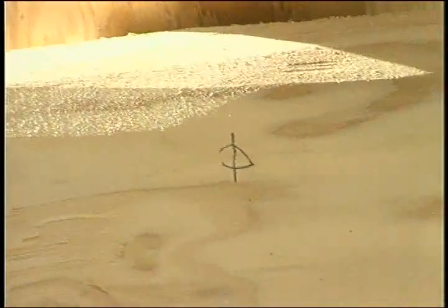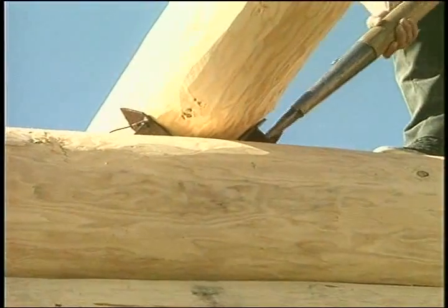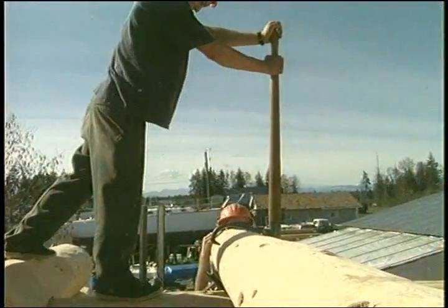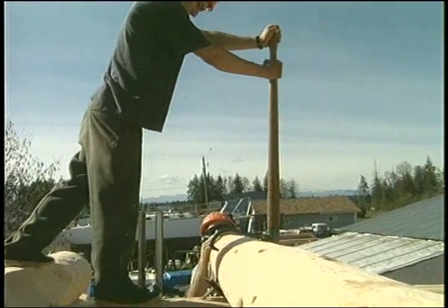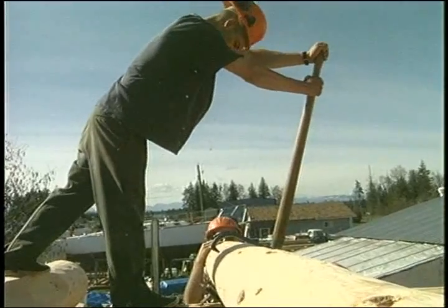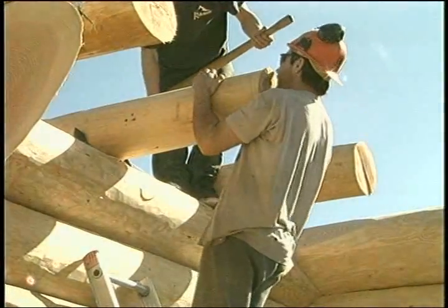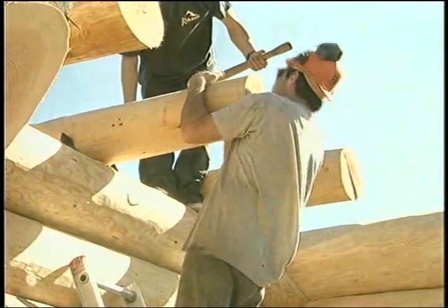Place the large end of the joist or beam accurately on your mark, then block it with rolling dogs. Shift the other end into place and dog that end also. Roll the log until the very best straight side is up, then dog it securely with drive dogs, only at the large end. Do this same operation with each joist.